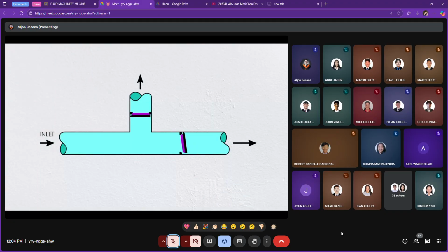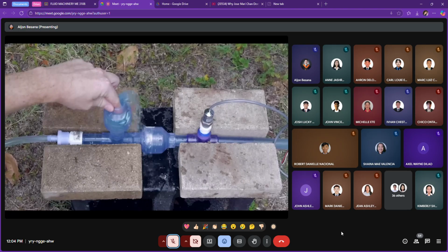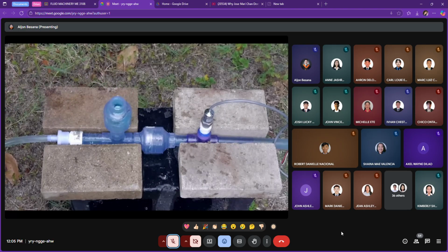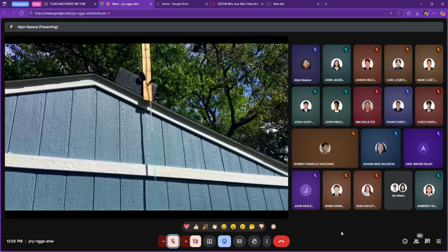A ram pump is essentially just 2 one-way check valves, one called the waste valve and the other called the delivery valve. To get it started, you just momentarily open the waste valve to allow water to flow. After that, it's working on its own to pump the water uphill above the elevation of the source. Pretty amazing, I think.